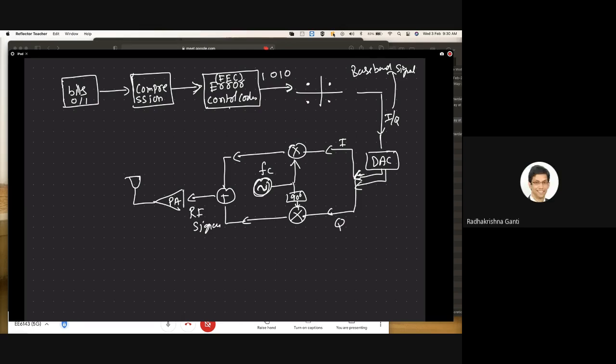Yeah, baseband signal. We can see even this is called baseband signal. Generally when we say baseband signal, it implies a digital baseband signal. So baseband signal means in general zero frequency, zero IF. That's a kind of mathematics where you have mathematical values for every set of bits. If it is say QAM 4, then all those 4 bits will become those mathematical things, and that will get converted into an analog signal. Am I right? Yeah, the DAC will convert it into an analog signal.